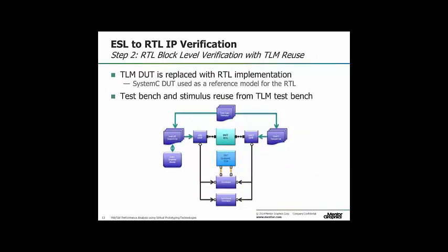It just helps with the process of building the framework and the stimulus, reusing the SystemC model, switching it out when the RTL becomes available, and helping with the verification of the RTL as we've got something already built that should have the same behavior.